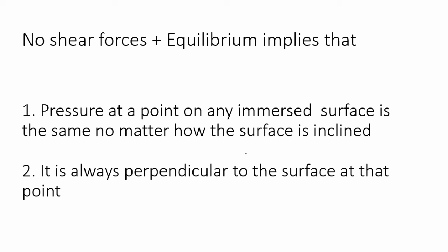Pressure, remember, I'm not talking about force, because force is the integral of pressure, but pressure is force intensity. So force intensity only depends upon how deep it is, not upon which way the surface is pointed, and it will always act perpendicular to the surface at that point. So if I have a surface like that, the force intensity here is rho gh and it will act that way. The force intensity here will be rho gh again, but a different h now, and it will act that way. So that's all you need to know about fluid pressure. Thank you.